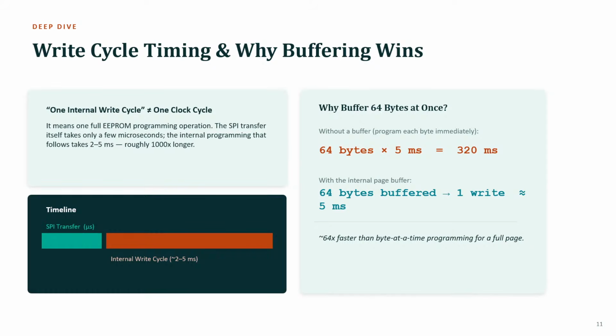Yes. So let's say, why buffer 64 bytes at one time? Suppose without a buffer we have 64 bytes of data, and for 1 byte of data we take 5 milliseconds. Then for 64 bytes of data we are going to take a total time of 320 milliseconds.